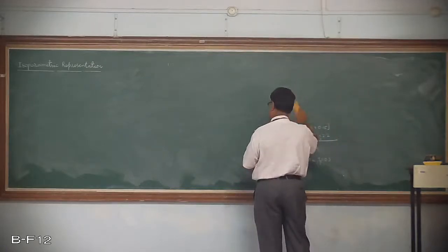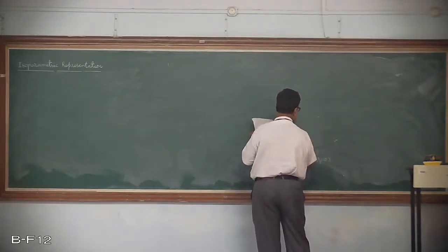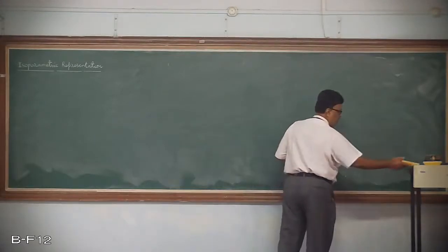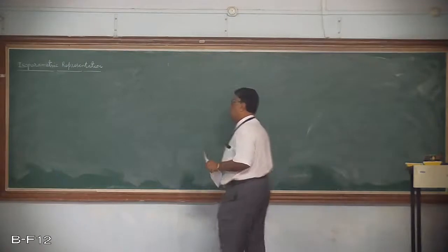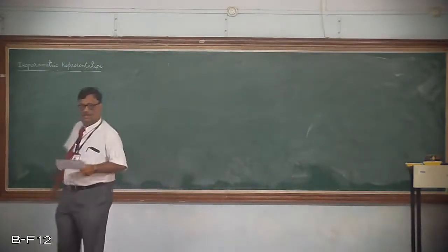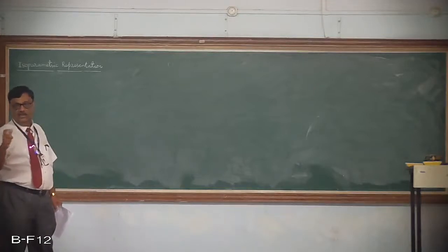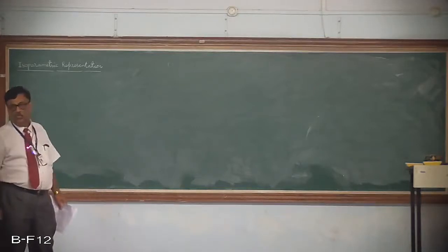Okay, the next interesting point is we have to develop a relation for the strain displacement matrix and the strain components, how to find out the strain components, and then later on we have to find out the stress within the triangular element. Since it is called a constant strain triangular element, the strain is constant throughout the element, and automatically the stress is also constant throughout the element.